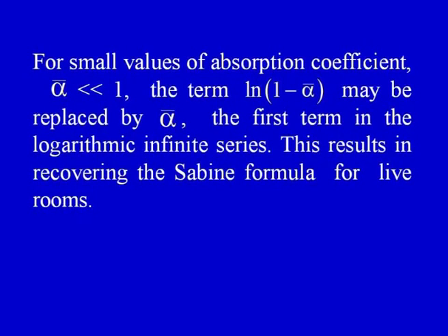For small values of absorption coefficient, alpha bar very small compared to 1, the term log of 1 minus alpha bar may be replaced by minus alpha bar, the first term in the logarithmic infinite series. This results in recovering the Sabine formula for live rooms.